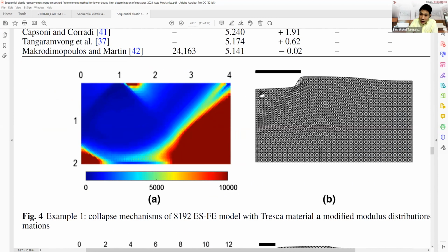The nice thing is that the more you discretize the mesh, the smoother the distribution of the displacement and the stresses. This is the von Mises stress, which shows the behavior of the stress transfer. We have the foundation with a uniform pressure applied. I just model it as half of the punch problem. So this is the boundary of the structure you're looking at, and I take only half of it. The loading will be somewhere that I put my hand on. When I push the loading, you see that it's deformed.